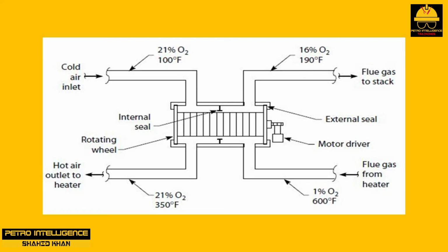In general, air preheater leaks are a problem because they reduce the thermal efficiency of the air preheaters, and may reduce combustion air so that it falls below that required for absolute combustion, resulting in destructive afterburn. Note that air preheaters themselves are often destroyed by afterburn. Leaks may also cause the forced draft fan to operate at higher flows, requiring higher driver horsepower.